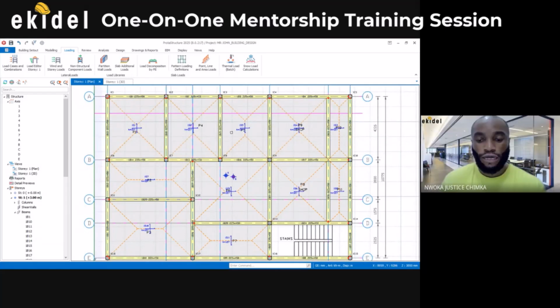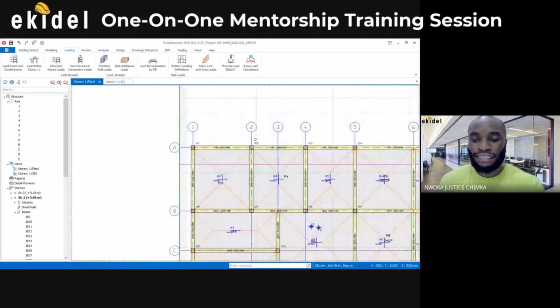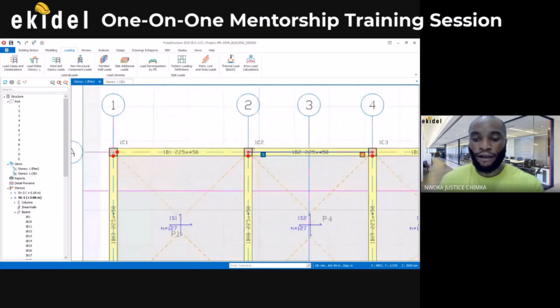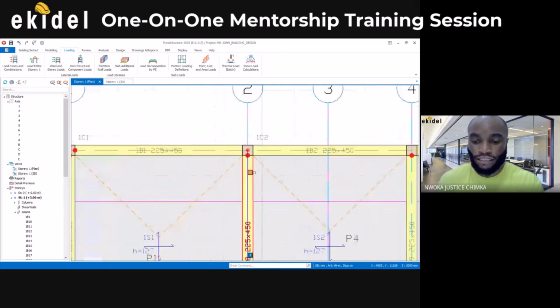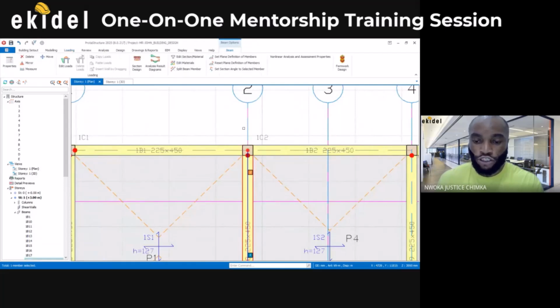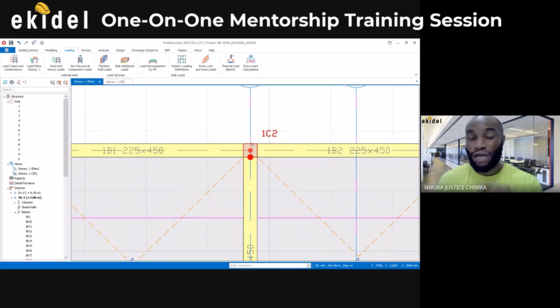Yes. Look at what I'm doing: I'm hinging every end of a beam, any end that doesn't have continuity of the beam. I will hinge there. For example, this beam does not continue after this column, so that means this is an end of beam. So I will hinge it.